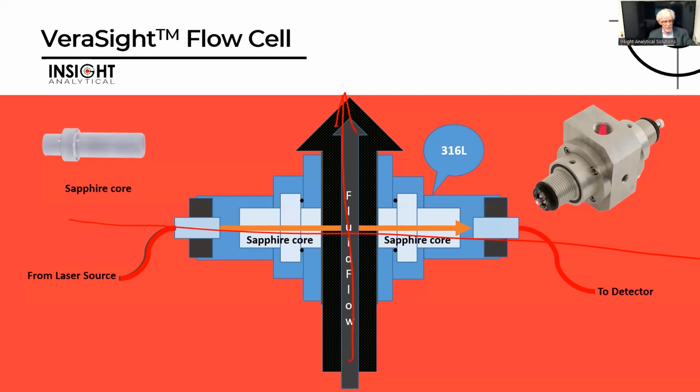The advantage here is, again, when I go to a conventional analyzer, I'll often have things like 1/8-inch tubing, little tiny micro injection valves. It's not a problem with the analyzer usually. It's a problem with all of the things that have to let flow get in and out of the analyzer. Doesn't deal with dirt very well. These sapphire windows, dirt doesn't stick to them that easily. You can just wash it off by running toluene through the cell or diesel or something like that. So it's really easy to clean the system. Nice big ports that don't plug.